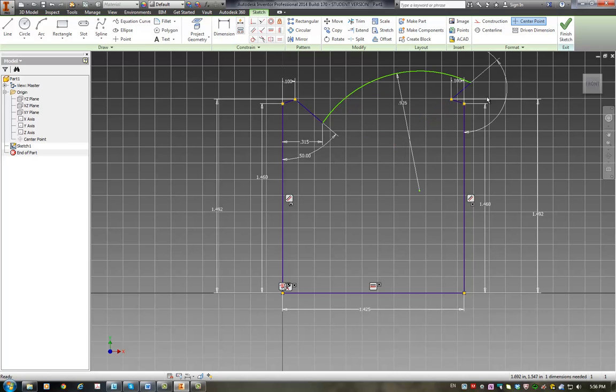And as you see, this is not really what I wanted to see. So I can go one step back, and before I change that, I can add another constraint to make these two lines equal, this one and this one. So I can say I would like equality for this line and this line. So this doesn't happen if I change it to 0.926. You see now it looks good because I said these two are equal, so it didn't go somewhere.